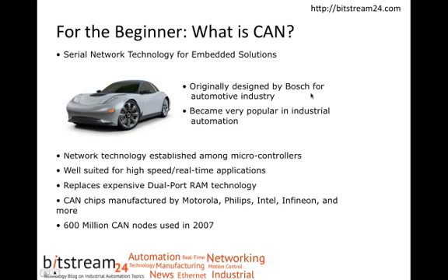Now, just as a reference for the beginner and for those who are more interested in the technology, a brief explanation of CAN. CAN is a two-wire half-duplex high-speed network system that is superior to conventional serial technologies such as RS-232 in regards to functionality and reliability. It prevents message collisions and provides excellent error detection and recovery.